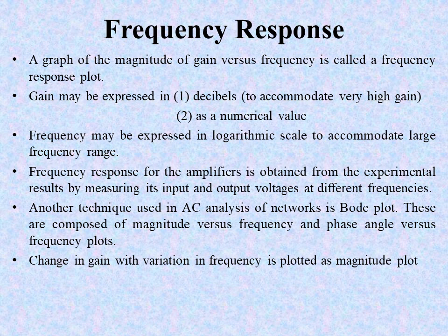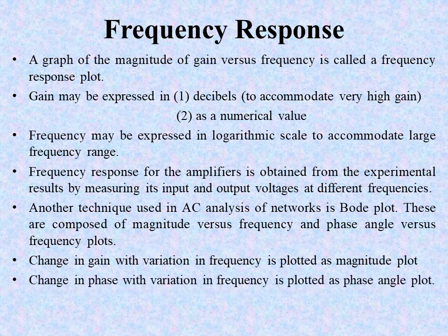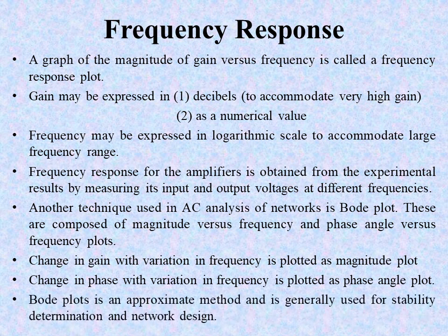So change in gain with variation in frequency is plotted as the magnitude plot, and change in phase with variation in frequency is plotted as the phase angle plot. But the Bode plot is an approximate method and is generally used for stability determination and network design. So for the frequency response of the operational amplifier, we generally use the experimental technique.